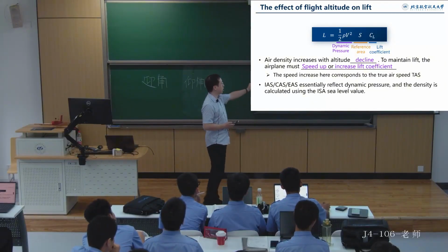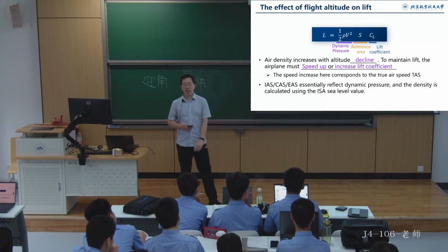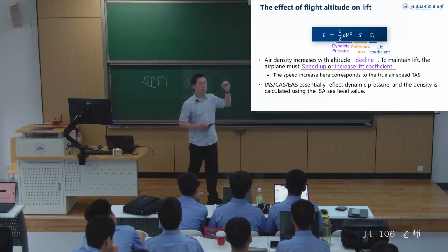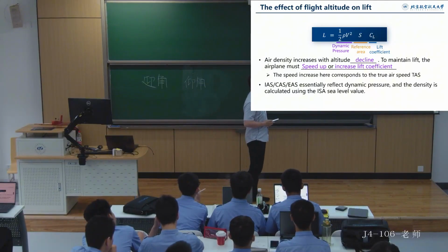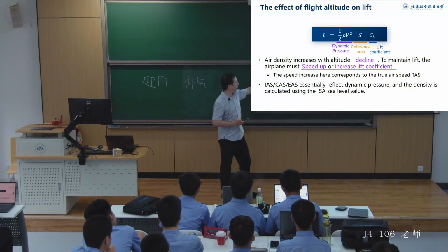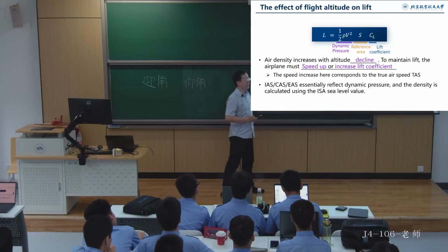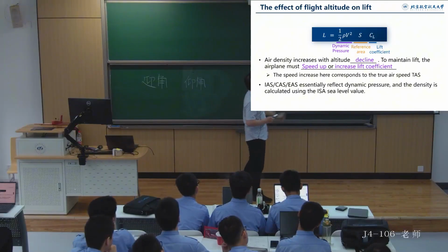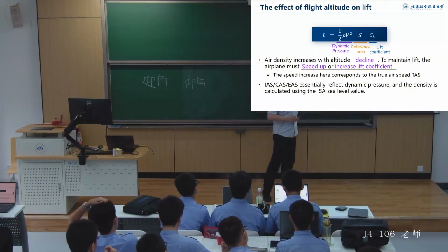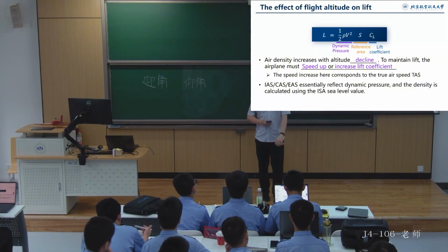Therefore, during the climbing process, when we are not manipulating the control stick and when climbing at a constant indicated airspeed, the dynamic pressure should remain unchanged. Or conversely, if we maintain the dynamic pressure unchanged while climbing, then only the airspeed should remain completely unchanged, right?